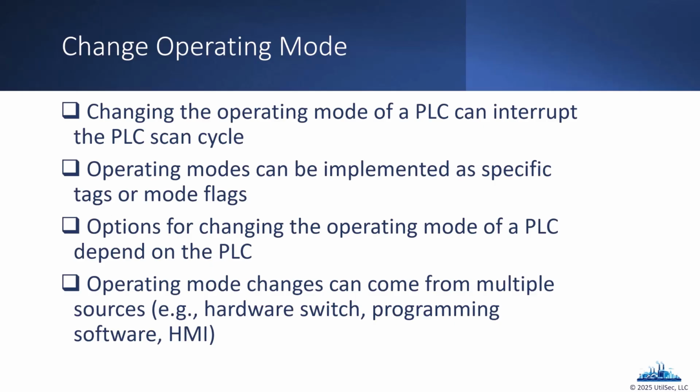So remember, as a brief reminder, when we have a controller like a PLC, when it's up and running and doing its thing, we consider that it's going to be in run mode. We should have that key switch we've talked about placed in run mode. So we can't have remote parties, at least, change the version of firmware remotely on the controller for us. But when you think about it, if I'm an attacker in the environment and I want to have an impact, there's a couple of ways I can do that by manipulating the operating mode of, let's say, a PLC.